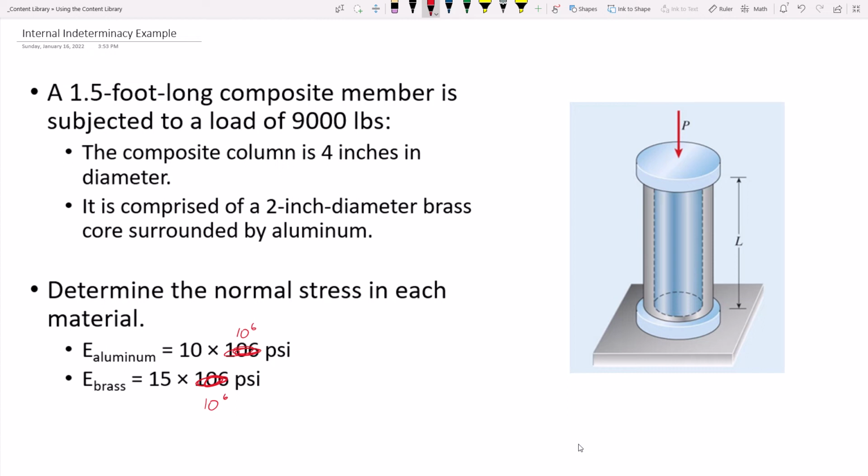Now, what we're going to see, and I'm going to talk about this here in a little bit. One of the things that you find in analytics, if you will, is that stiffness tends to be a magnet. When you have systems that are indeterminate and you look at the resulting stiffness, the elements that have the larger stiffness properties tend to absorb more of the load. If you ever get the chance, either you mechanicals or civils, to do some more advanced finite element analysis, if you're ever looking at some really large-scale finite element analyses, take a look at the stiffness properties and take a look at the resulting stresses. And stiffness kind of acts like a magnet. It kind of sucks in the load in a given system.